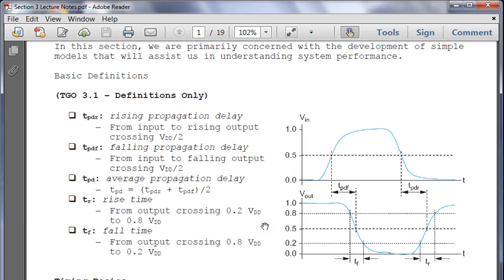In an ideal circuit, the rise and fall times are the same. In order to make that work, you actually have to change the transistor widths to make it match, and you have to do some restoring and buffering and consider how body biasing impacts this.